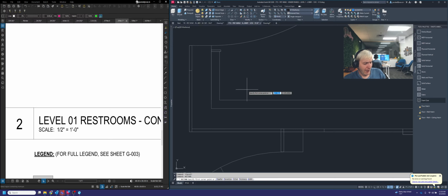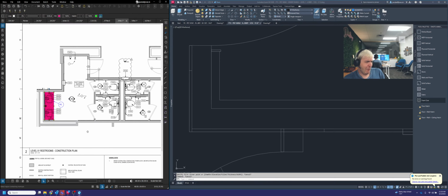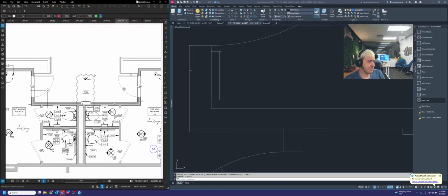So, just like we talked about before, with our standard panel construction, we always need to have a 1-inch gap between the drywall and the back of our panel. And that's if you're using panel cleats. If you're using Z-clips or Z-bar, you will only need a 1/2-inch gap between the back of the panel and the wall. This time we are using panel cleats, so we need to make sure we show that 1-inch gap.